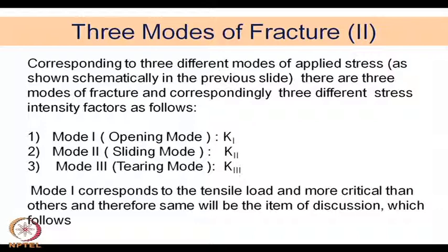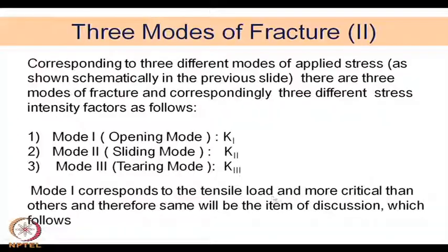Now, mode 1 corresponds to the tensile load, and the other ones are shearing modes. Mode 1 is under tensile load and more critical than the others, therefore it will be the item of discussion that follows. Most of the time, whenever we discuss fracture toughness, it is this kind of fracture mode we will be concerned with, because that is more critical than the others.